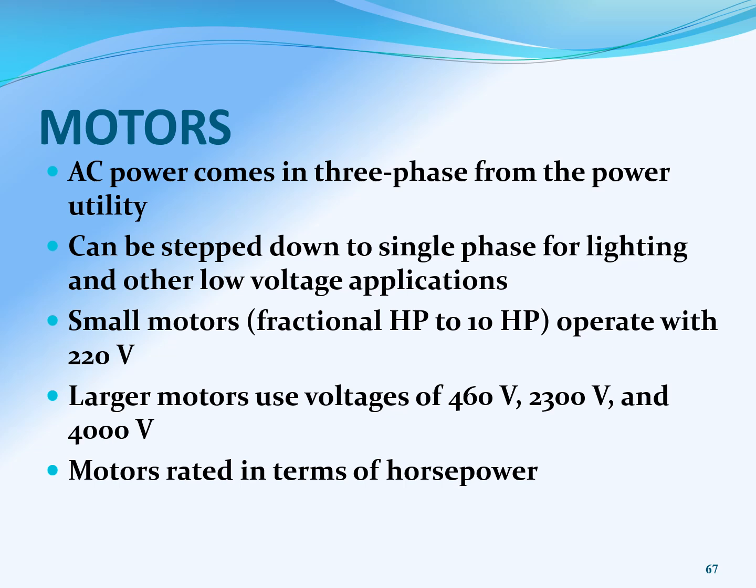What kind of power do you have coming to you? Because if you're sizing a large motor but you don't have adequate power supply, you're going to find out real quick that you've got issues. That's a lot of stuff that gets figured out in the design phase. And then lastly, motors are rated in terms of horsepower, which we're going to talk a little bit more about here.